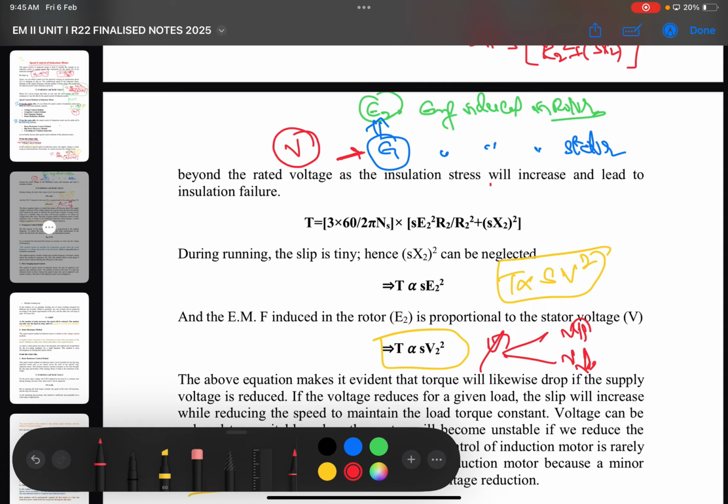Similarly here, if I increase the voltage level at the input side, now the insulation of this cable is 260 volts. Now I'm increasing the voltage from 230 to 300 volts. Will the insulation strength be capable of balancing that voltage? Yes or no? Already the fixed voltage is 230, and that's why the insulation of that cable is given as 260 or 270. Now by some means I am increasing the supply voltage to 300 volts. Will the insulation voltage change automatically?